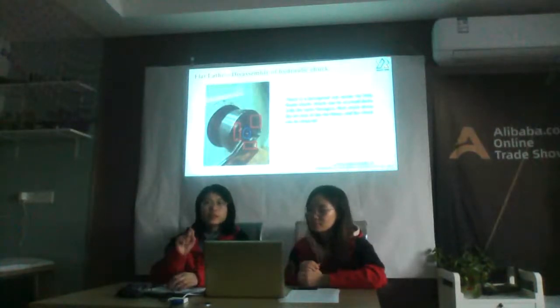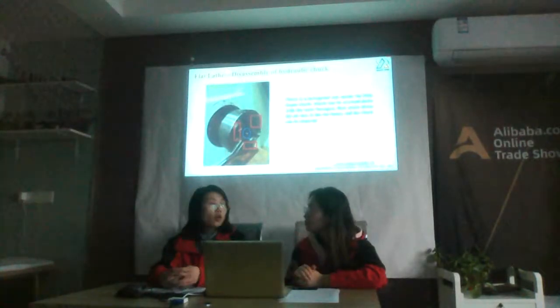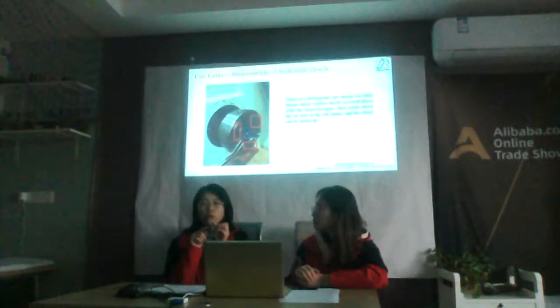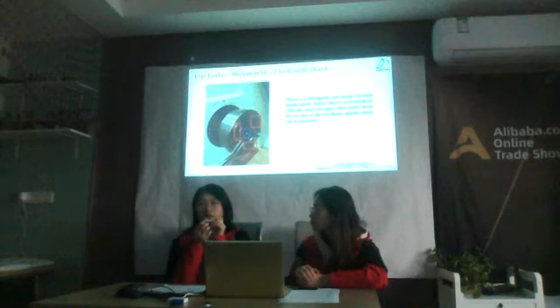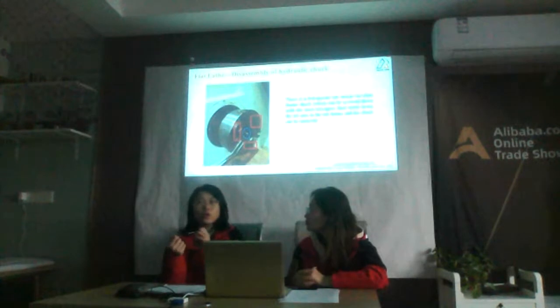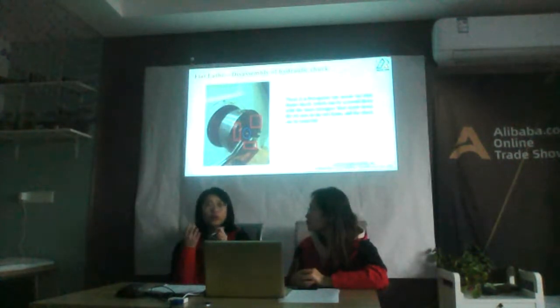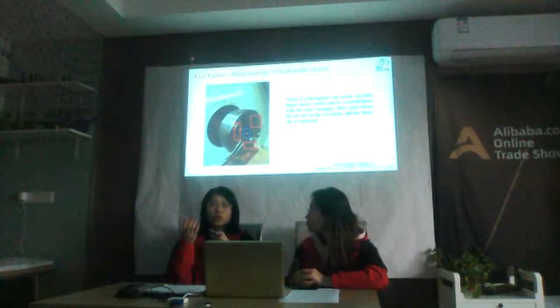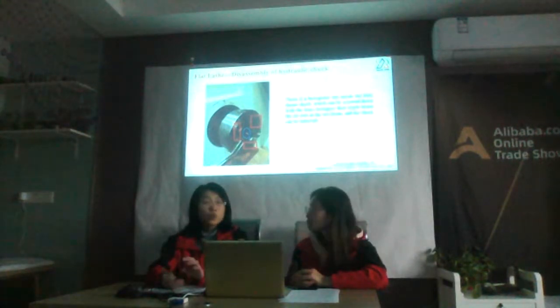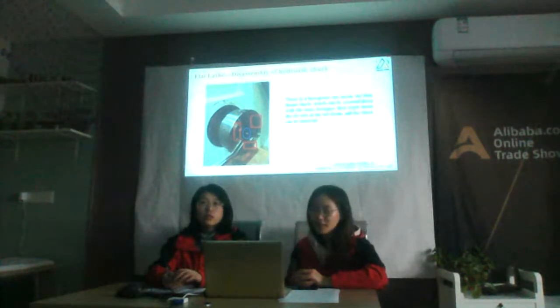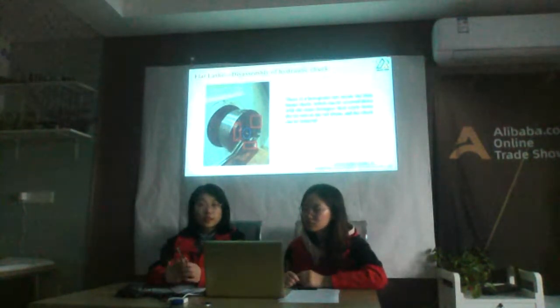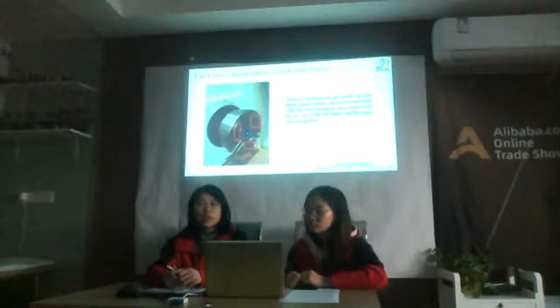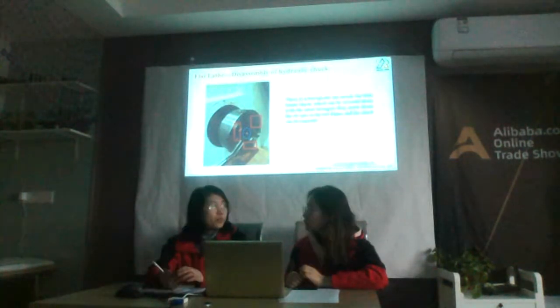And pay attention. One more thing we need to talk about the hollow chuck. The first one, we need to know the workpiece diameter, the workpiece size, so that we can equip the right one according to your workpiece. And you can also let me know the chuck through-hole diameter. If you don't have your workpiece size, you can let us know, so that we can equip the right central hollow chuck with the machine.